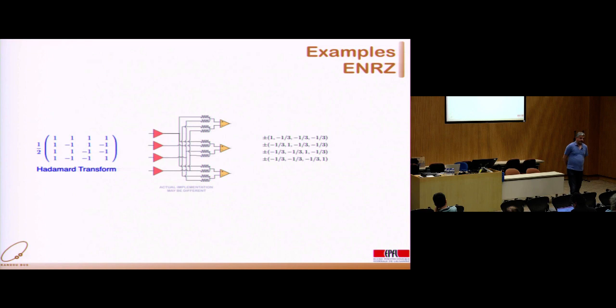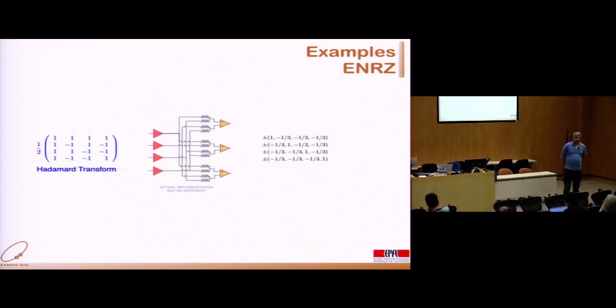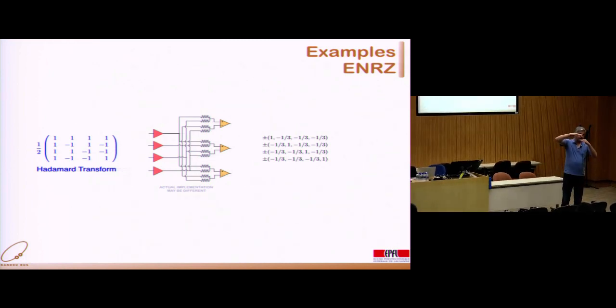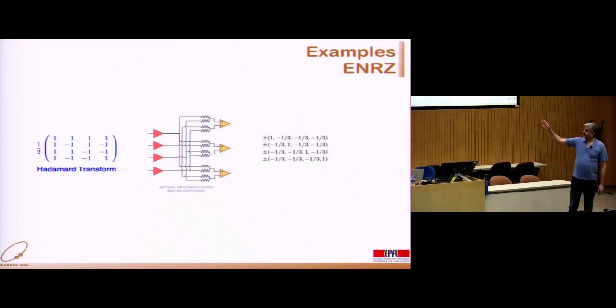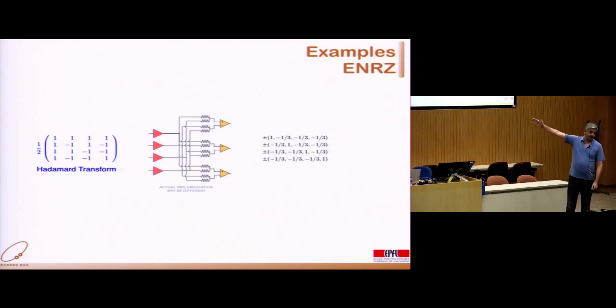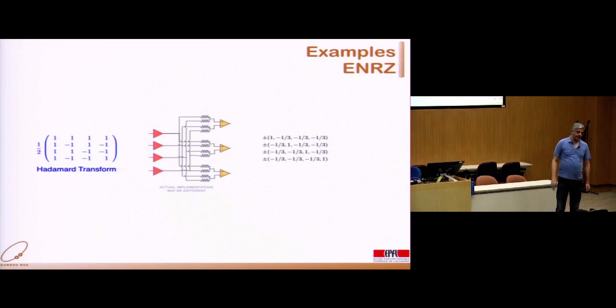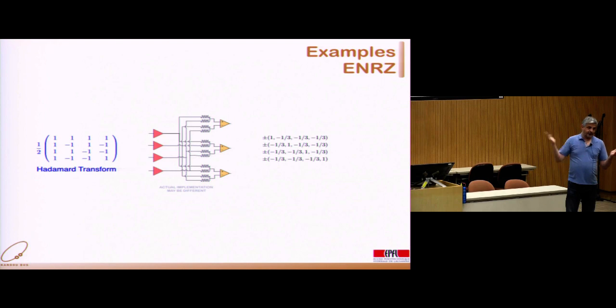I'm just saying that from a philosophical point of view, there's no free lunch, so what are we losing here? The only place where you lose is what's called the vertical opening. It's difficult to explain, so let's put it this way. If you had equal throughput over the 4 wires, then the vertical opening here is still better than what you would have with differential signaling. If you have equal frequency, which means differential signaling has 2/3 of the throughput of here, then the vertical opening is smaller than what you would have with differential signaling.